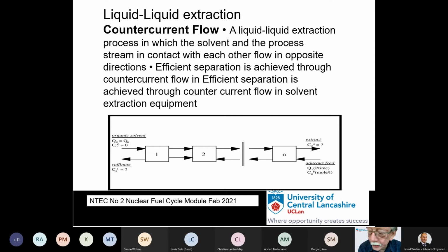And as I said earlier, ion exchange is important in uranium mining, irrespective of the leaching process, which we'll discuss after lunch. The actual operations at Springfields, when we used to operate a uranium refinery there, and still, but with Magnox only at Sellafield, the actual process we use for recovering and purifying uranium and plutonium at Sellafield, and as we use to purify uranium at Springfields, is this process called liquid-liquid extraction.